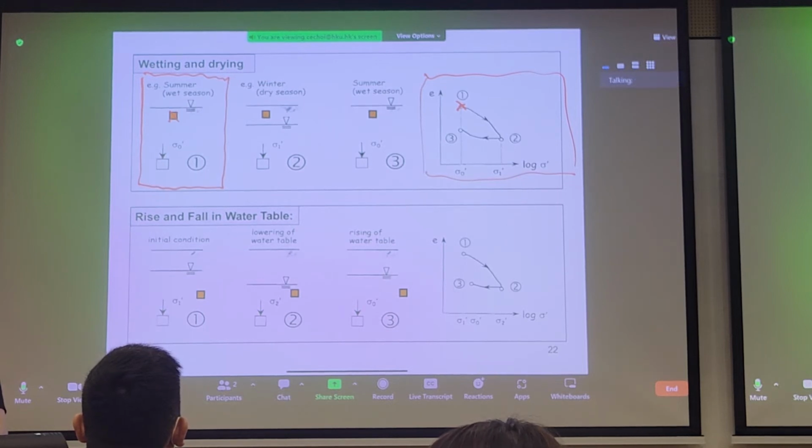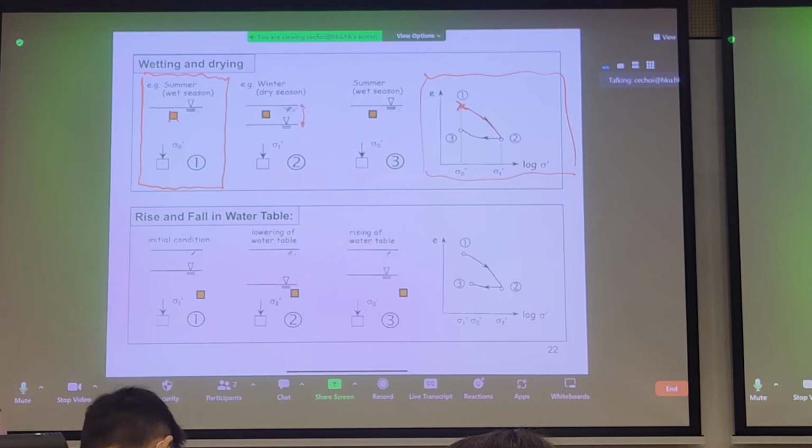And then in the winter season, the groundwater table will recede or decrease. And we know that with the reduction in pore pressure, we get increased effective stress. And let's say this is the first time the slope has experienced it, and we generated quite a bit of excess pore pressure initially on this natural slope, okay? And then we get increase in effective stress, and you get substantial void ratio change, which is probably not so realistic, but just let's make a few assumptions here.